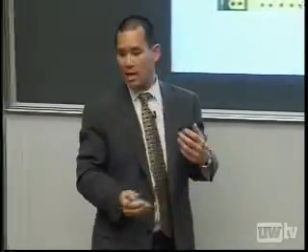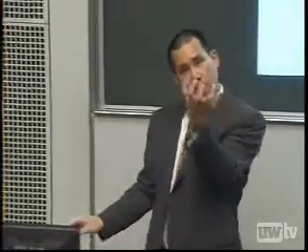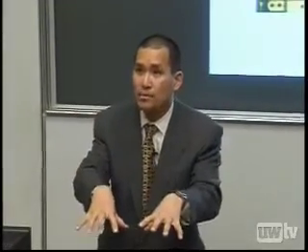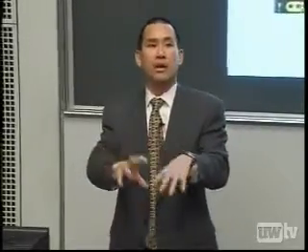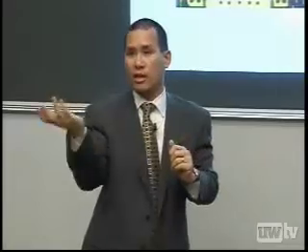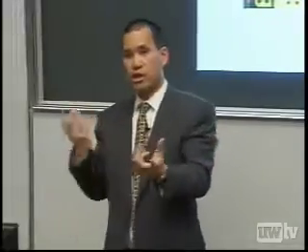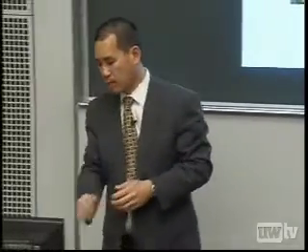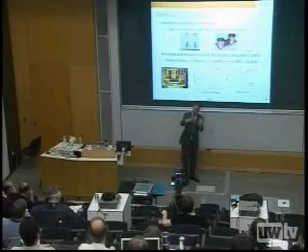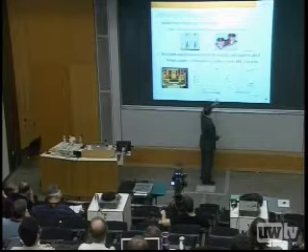And so we can think about taking substrates that have these claws on them, taking our array of chips and putting them onto that substrate. You get a nice temporary connection, the claws dig in, and you test them. You can test them at speed because you can deliver enough power through the claws. If they don't work, well, you take that chip, you put another one in, and you keep going. You better be able to cool it because we're thinking of putting lots of chips into a relatively small space. So here's an example of a cooler on the right.